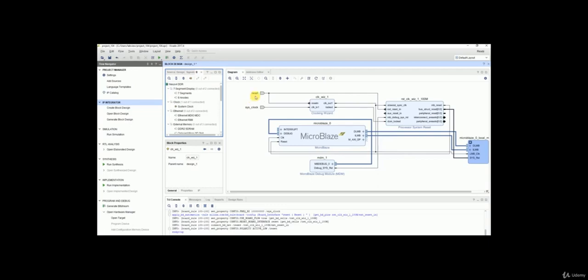So you'll find the system clock has a check mark, which indicates that we have connected the clocking wizard IP to the correct source. The second verification check is to verify whether reset has also been connected to the board reset. You will find the board has a reset pin, and right next to it we have a check mark.